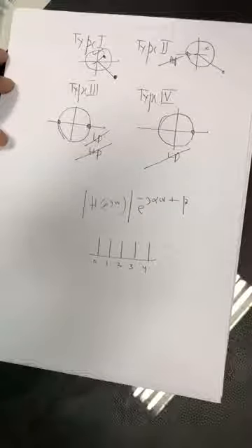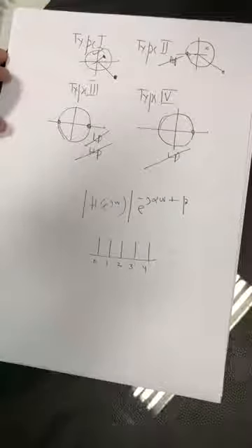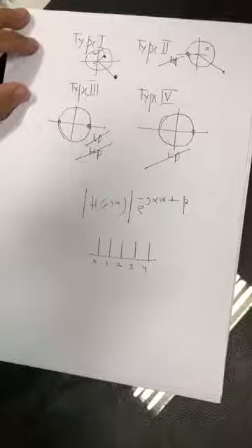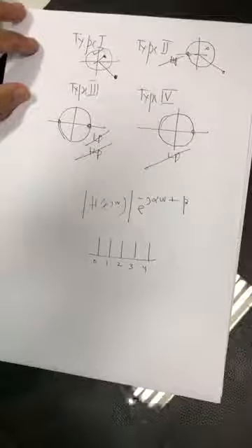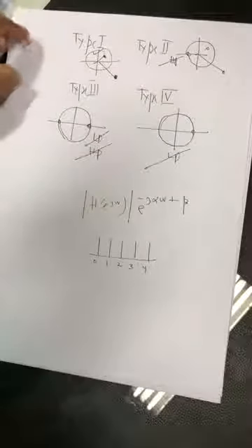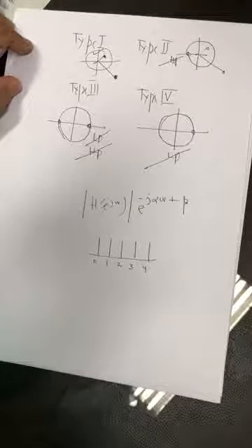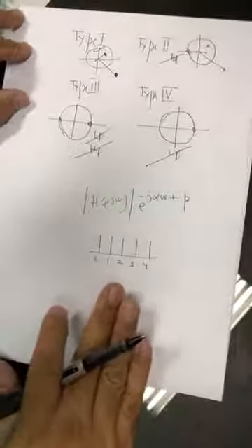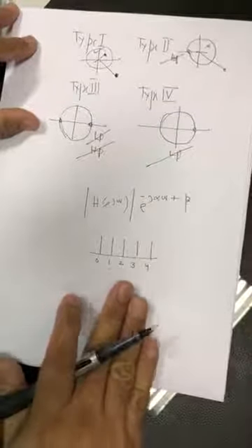Okay, and the poles or the zeros on the unit circle will not let frequencies pass. So by just looking at the linear phase FIR filter plot, we can tell what is actually happening there. So this is type 1 linear phase FIR filter.